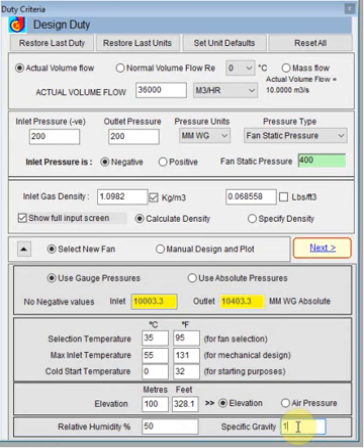So for a heavy gas we might put 1.1, and we've got now a high inlet gas density. So 1 is the standard, which now gives us a much lighter gas density. Now often a system designer will specify this density, so we can simply check this box here and say that it's 1.2, which was the figure specified by the designer. So now we can go on to click Next and select Accessories.